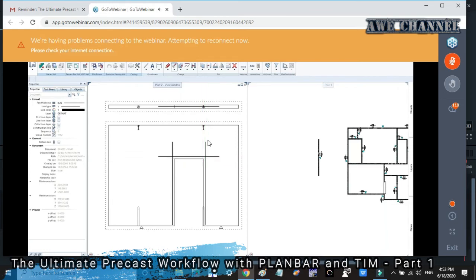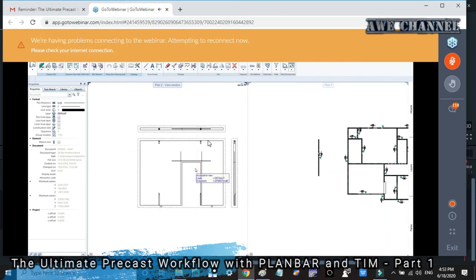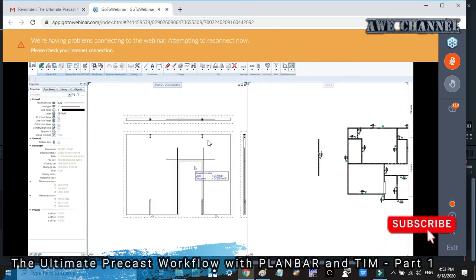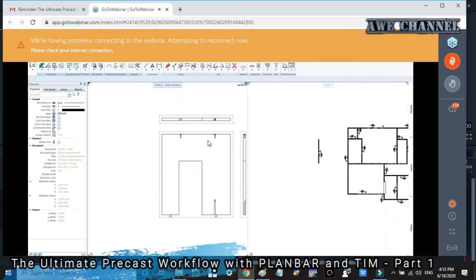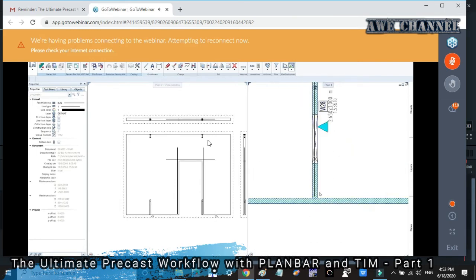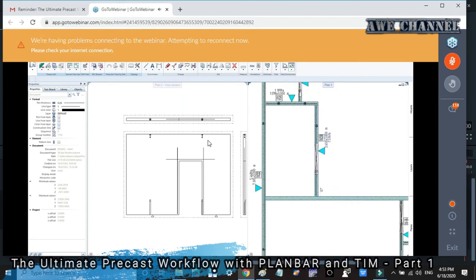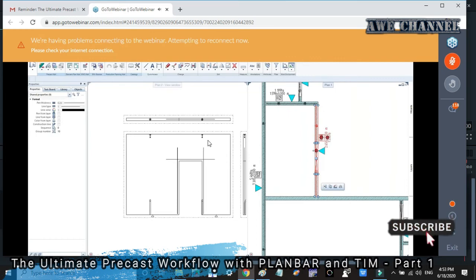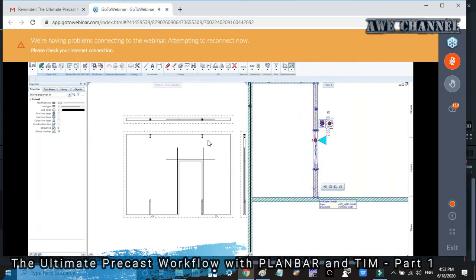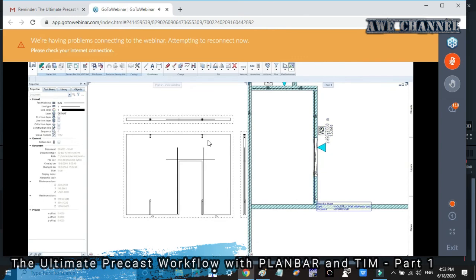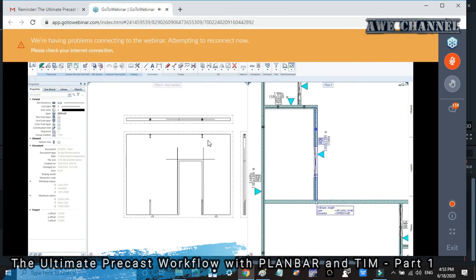Sorry, may I jump in shortly? Here you have seen exactly what happened before. If the 3D walls are connected together, there is very strict control that you cannot even extend it. That is very important, just to mention it. Yeah, thank you, Yusuf. Because the walls are connected together, you have no possibility to add or merge a new wall into the existing elements because of the clash between two walls.